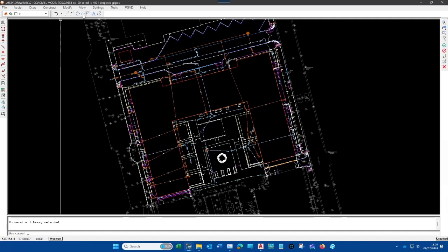Don't know why they call it string, but it is. And in terms of doing your work when you're drawing your 3D information, so your buildings, your footpaths, whatever have you, I would highly recommend using strings, because PDS is built to manipulate strings, not lines.